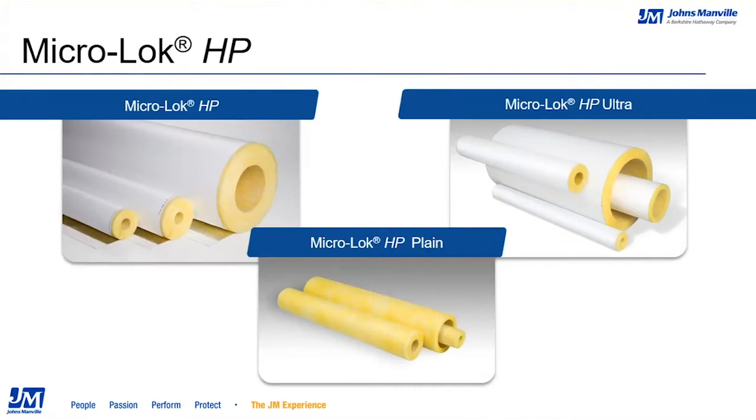Microlock HP is offered with an ASJ, or an all-service jacket, which is composed of an outer layer of bleached kraft paper, a reinforcing middle layer of fiberglass scrim, and an inner layer of aluminum foil. Microlock HP Ultra is offered with a polypropylene-coated ASJ jacket that includes all of the same layers as ASJ, but with a polypropylene coating on the exterior that supports better moisture resistance and cleanability.